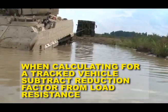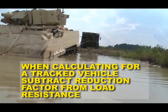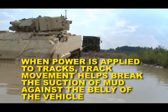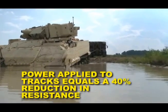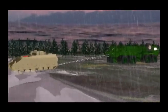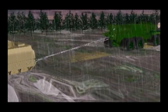When calculating for a track vehicle, you must subtract the reduction factor from the load resistance before moving to the next step. When power is applied to the tracks of a mired vehicle, the movement of the tracks helps to break the suction of mud against the belly of the vehicle. Power applied to the tracks equals a 40% reduction of resistance. When a mired track vehicle is recovered in the opposite direction of its travel, the tracks pass through ruts made by the vehicle when going into the mire. Recovering it in the opposite direction of travel equals a 10% reduction of resistance.